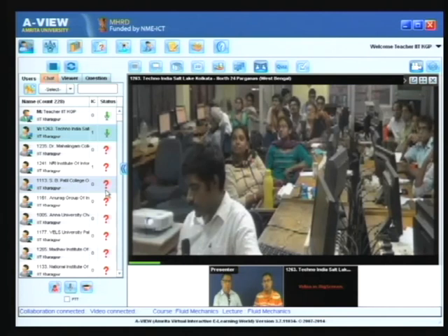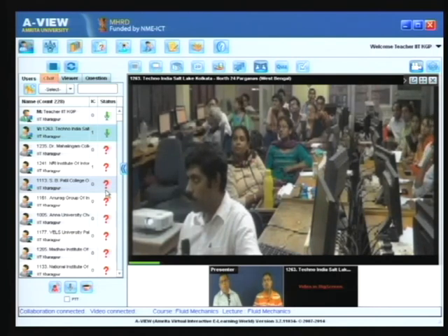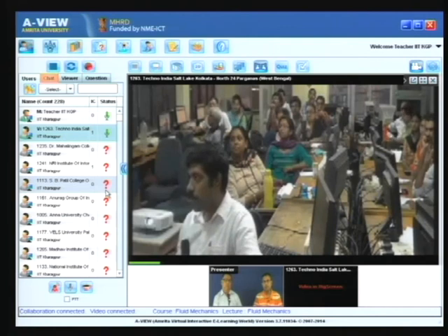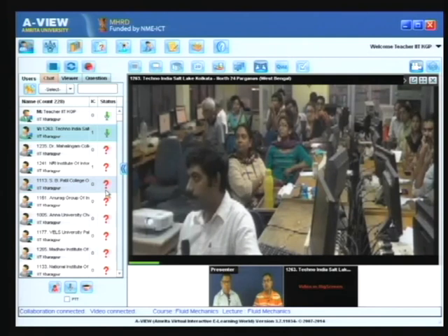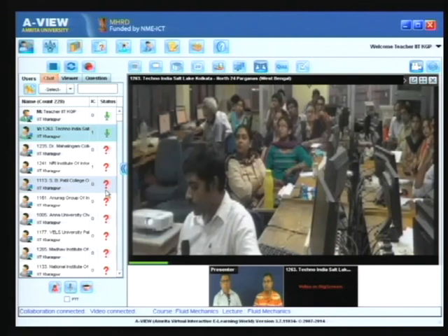So the total change in pressure from these three components is a sum of the change in pressure due to x, due to y, and due to z. This is true even if pressure is a function of time. This is a very important concept to keep in mind. These are just the three components of the pressure gradient coming into the picture because of the force balance along the three directions. There is no force balance in the time direction.